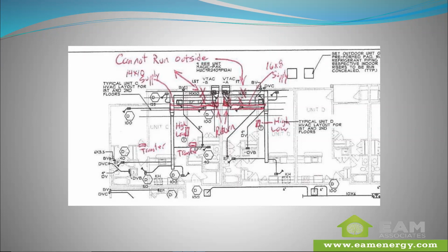There were no equipment schedules, which is also, I think, a really terrible idea. The note that you can see there in the top center, calling out the 9E Magic Pack unit with the model number, constitutes the whole of the plan callout for the heating and cooling system selection. So, that's not good.